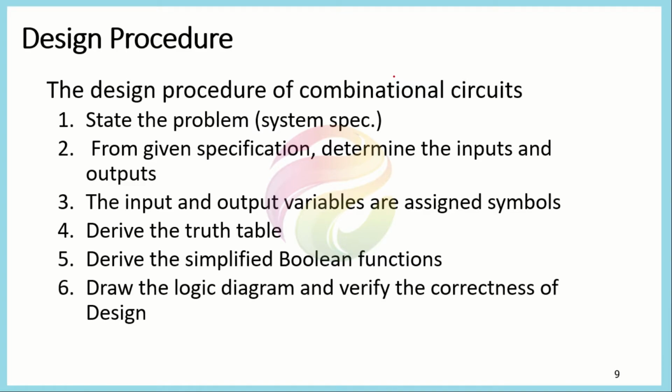The design approach, or the synthesis approach, is the more straightforward of the approaches, the one we are used to. In this approach, we are given a certain problem, and from that problem we first identify or specify what the inputs and the outputs of the system will be. And then we assign certain variables to the inputs and the outputs, and then we draw the truth table between these sets of inputs and outputs.